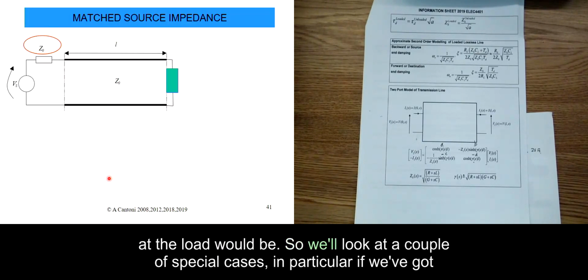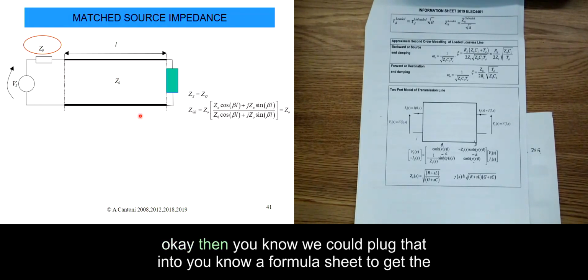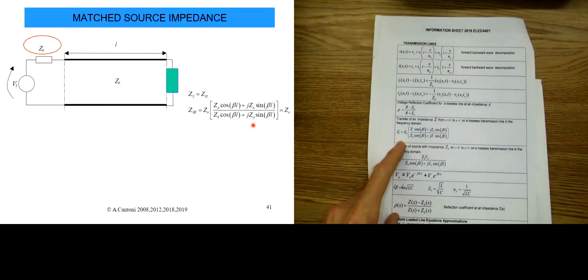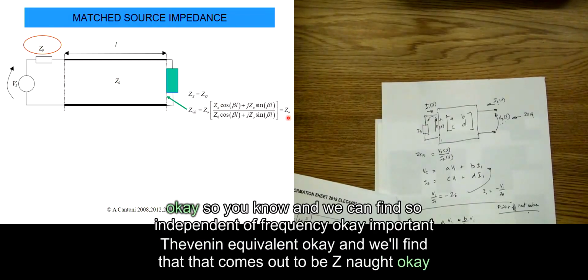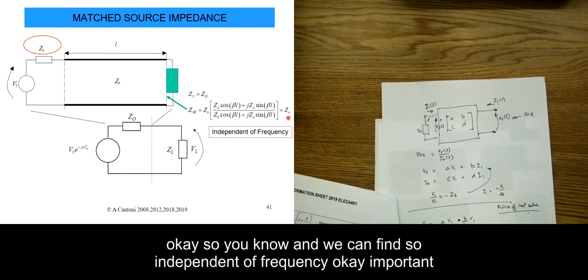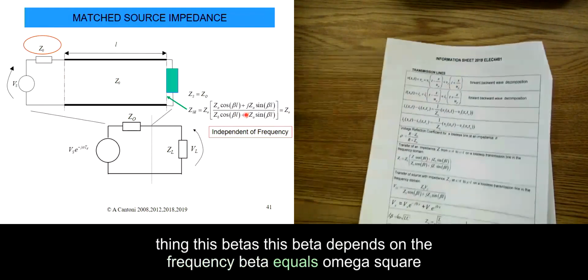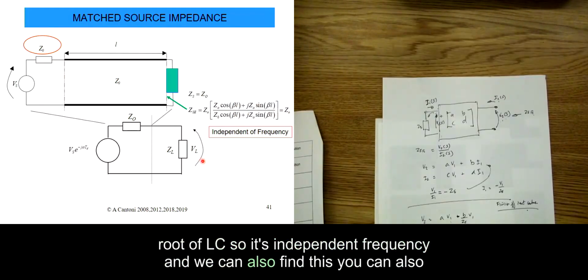So we'll look at a couple of special cases, in particular if we've got a matched source impedance, both in the frequency and the Laplace domain. If ZS equals Z naught, then we can plug that into our formula sheet to get the Thevenin equivalent, and we'll find that comes out to be Z naught. So it's independent of frequency. That's an important thing, because beta depends on the frequency: beta equals omega square root of LC.